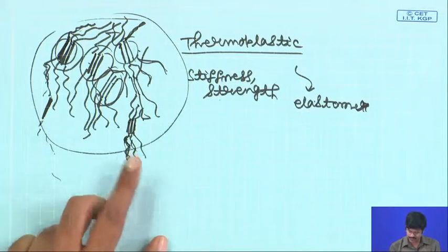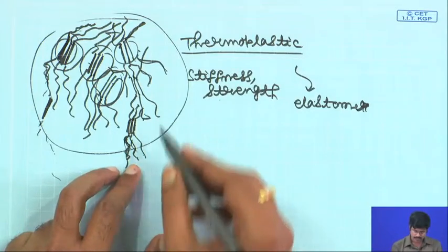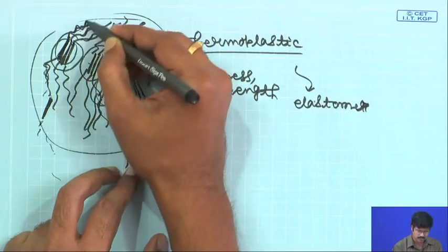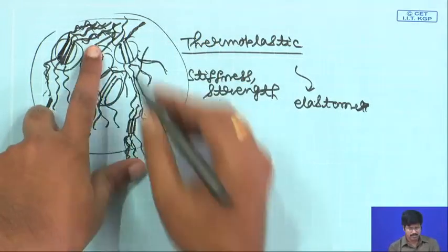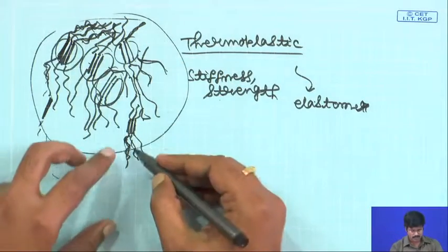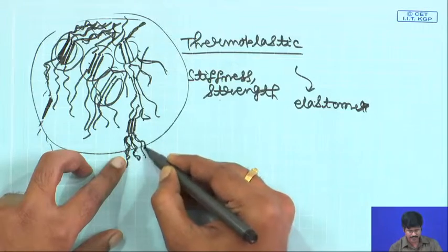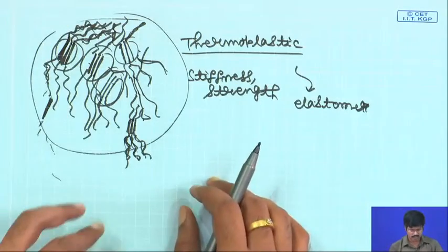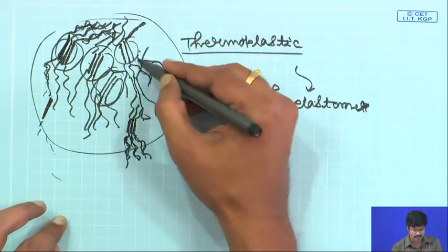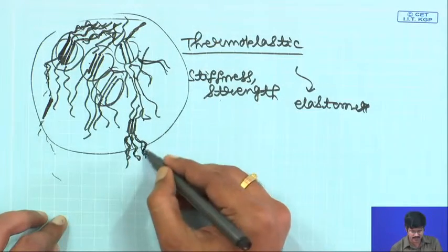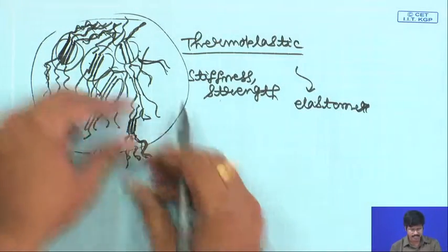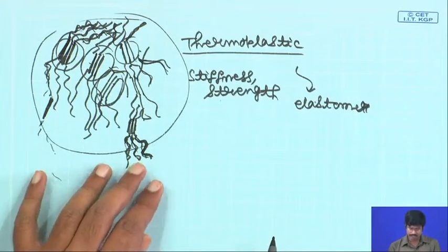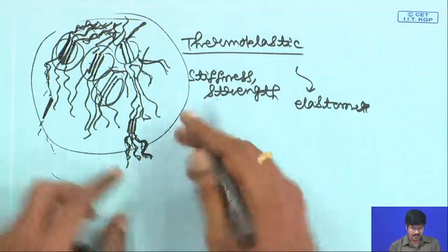Now, these soft segments are coiled sometimes like this, or they are wavy like this. So, when you are extending this material, until these soft domains are extended to their full length, you could continue to extend. So, what will be the breaking point? It is the point at which all these flexible chains become straight. So, basically you can say that these flexible chains contain hidden length. So, they can be extended. From there your stretchability will come, because your material is stretchable.